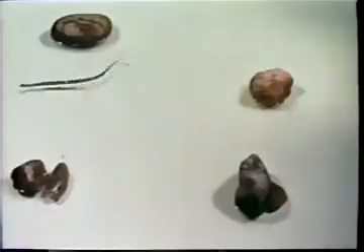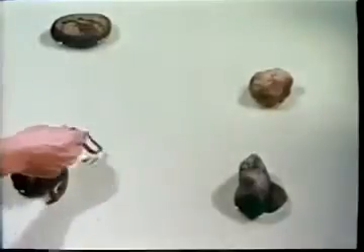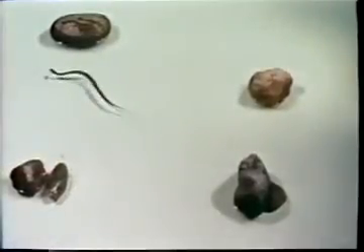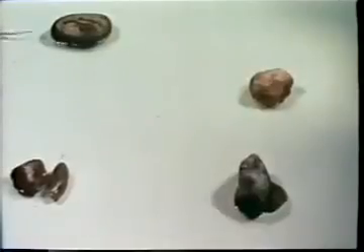Microscopic creatures, which may have Reynolds numbers as low as 1/10,000, cannot derive any appreciable thrust from inertia. They rely on moving their bodies in such a way that they derive their thrust from viscous stresses. The tails of these bull spermatozoa move like those of tadpoles or snakes by sending waves of bending backwards so that each section moves obliquely in the fluid. Here, however, the viscous reaction to the motion pushes on the tails in the same way that it pushed on the obliquely falling rod.